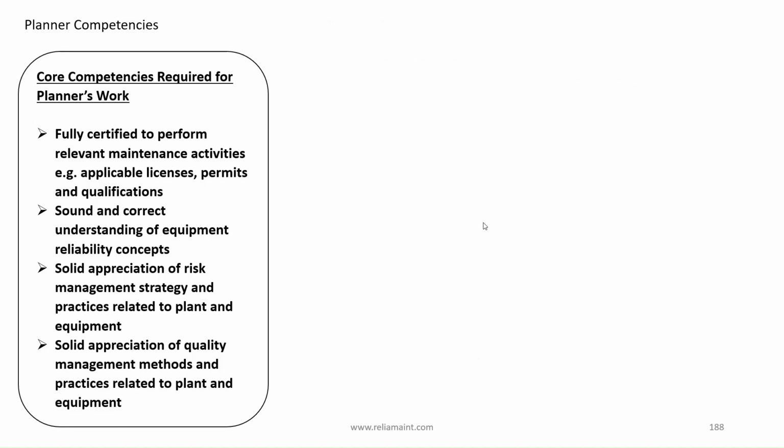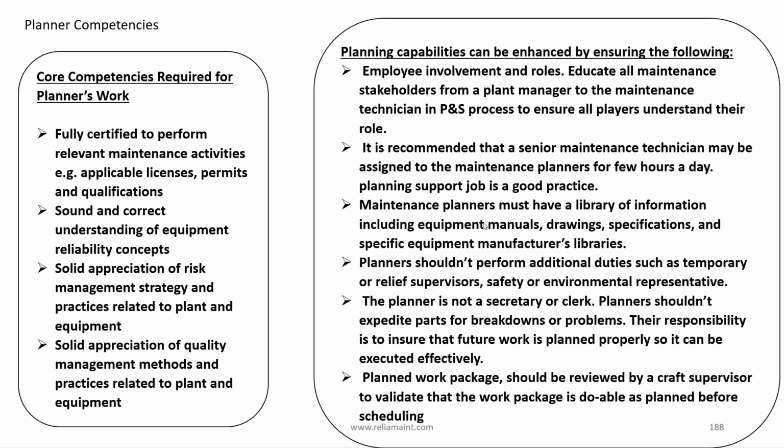Planning capabilities can be enhanced by ensuring the following: employee involvement and roles. Educate all maintenance stakeholders, from the plant manager to the maintenance technician, in the P&S process to ensure all players understand their role. It is recommended that a senior maintenance technician be assigned to the maintenance planners for a few hours a day. Planning support job is a good practice. Maintenance planners must have a library of information including equipment manuals, drawings, specifications, and specific equipment manufacturers' libraries.